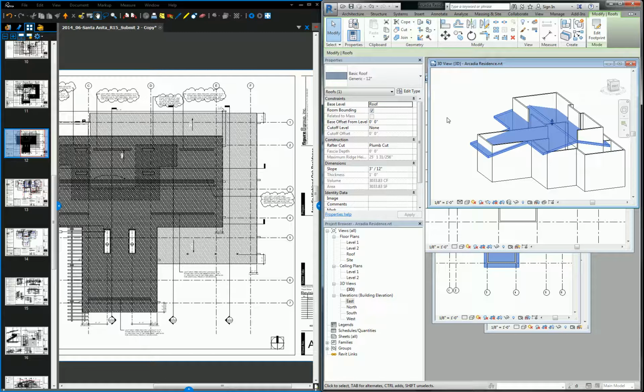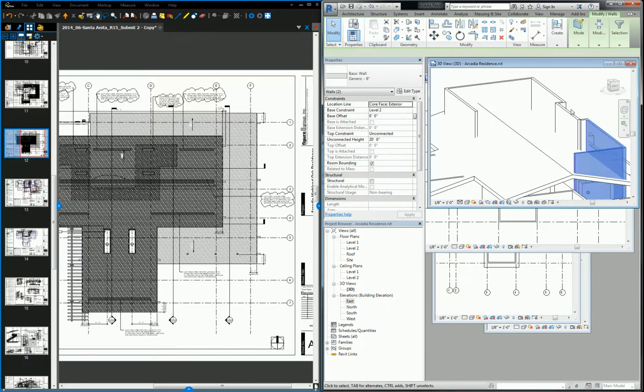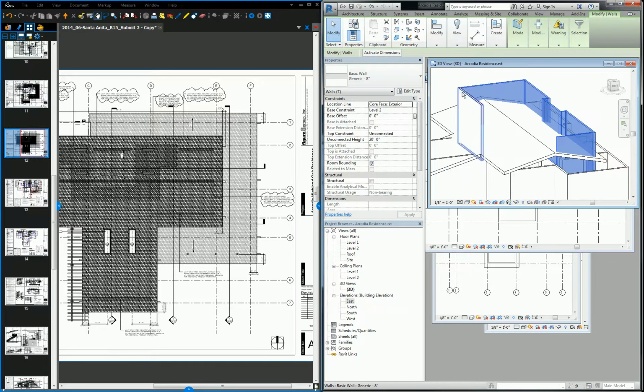It's a control thing. If you let it do it automatically, I guarantee you there will be walls that you don't want to connect that will connect. Promise you. So all you need to do is just select the walls that you want to have associated with it. And it is definitely a manual exercise, but it's fine.